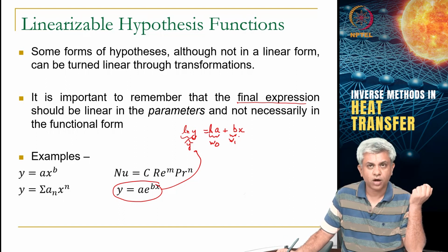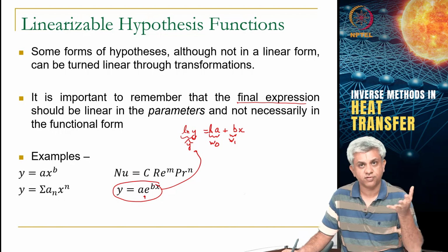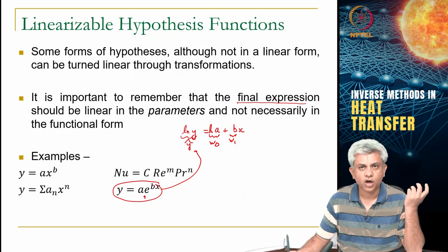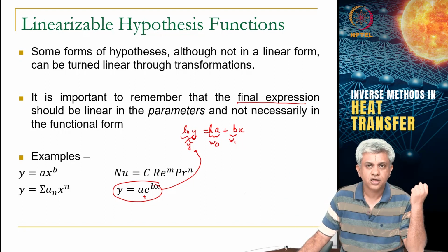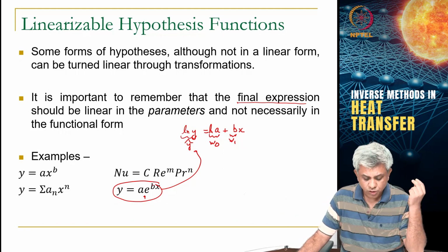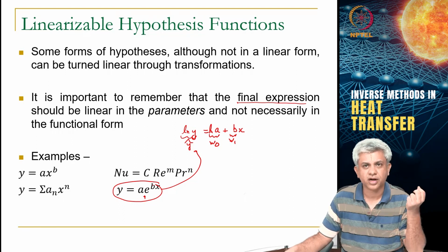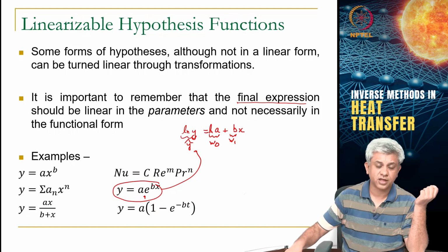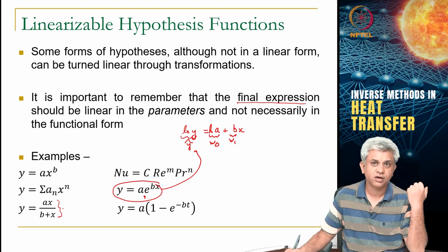As I also told you within this week, this form can occur within fins. We are taking simple cases. So, for example, a fin with an infinitely long condition, basically meaning that it is much longer in comparison to its thickness, in comparison to its width. So, in this case you can actually use this approximation, and at least we will see some exercise problems etc. as we go on in the course in such cases. You could also have things that do not look linear here, and if you carefully handle it, as I showed you this week, you can turn it into something linear.